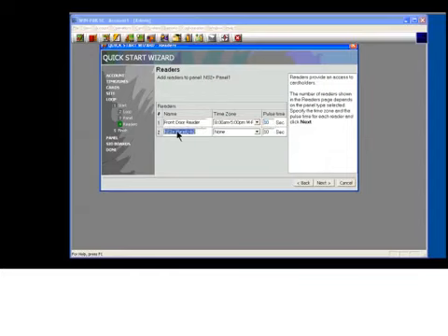We'll take care of our second door. This is a 2-reader panel. We'll call this backdoor reader. And for the backdoor reader, maybe the customer said, I want that door to always be locked. So in this case, we have 2 choices. We can put the word none in there. If there's no time schedule, the door will not open. If we put always on, the door will always be unlocked 24 hours a day, 7 days a week.